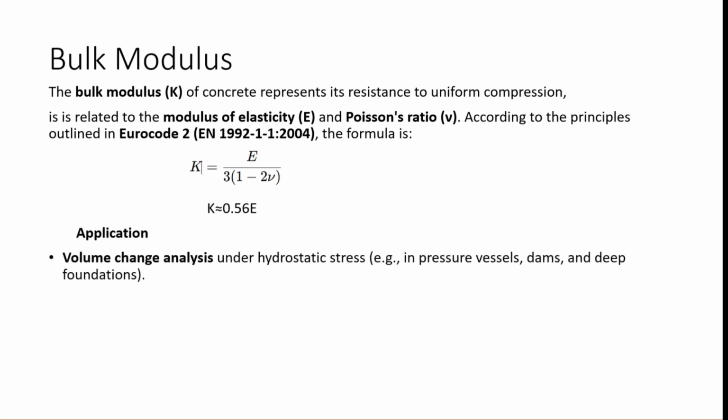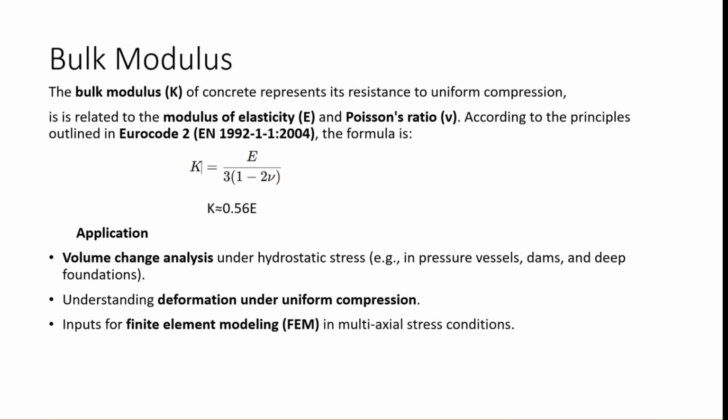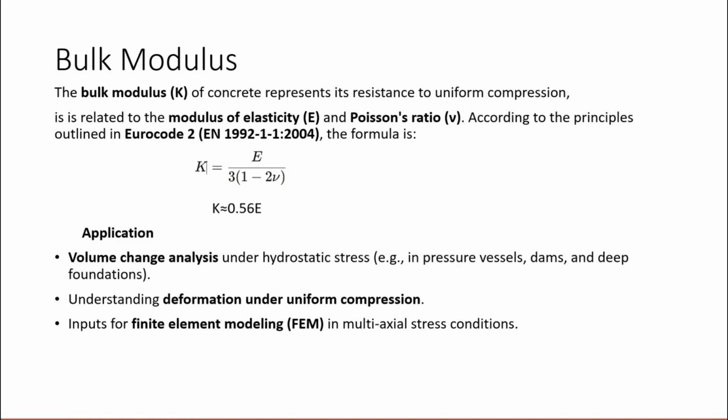What are some of the applications of the bulk modulus? The bulk modulus is used to assess the volume change analysis under hydrostatic stress, for example in pressure vessels, dams, and deep foundations. It is used in understanding deformation under uniform compression. The bulk modulus is also used as inputs for finite element modeling in multi-axial stress conditions.